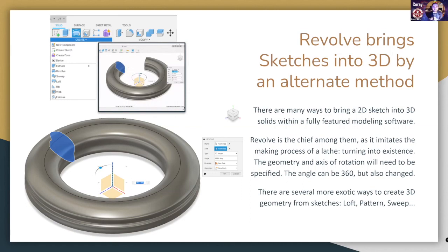And there's even a set of tutorials that wander you through these different tools that fall into the Create tab on Fusion 360, where you can create extrusions, revolutions, you can use sweep, loft, rib. There's a bunch of other ones that you can do. And I think that it's neat to explore all of these. Sweep is a cool one where you can draw a shape and then you can draw a second shape in another dimension and then follow out strange paths. We're going to see a sweep in a little bit. But there's lots of different ways that you can make things.